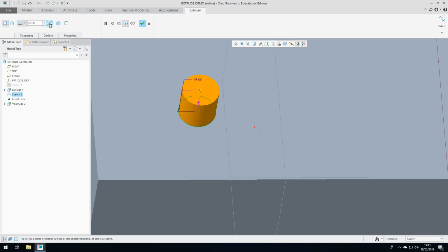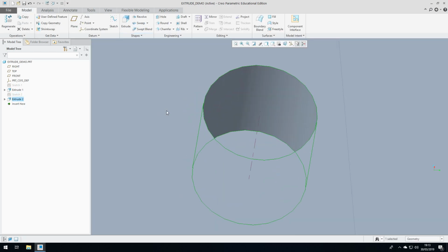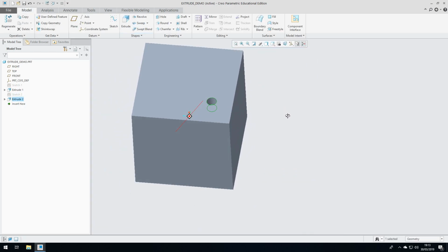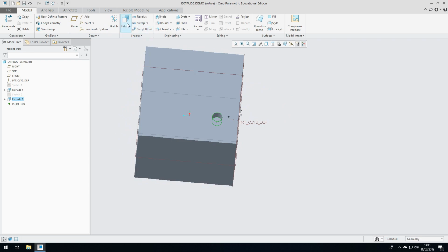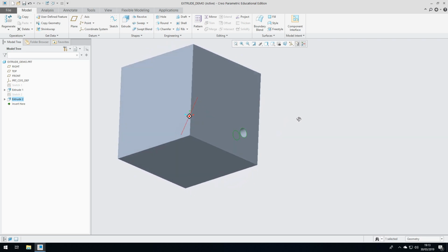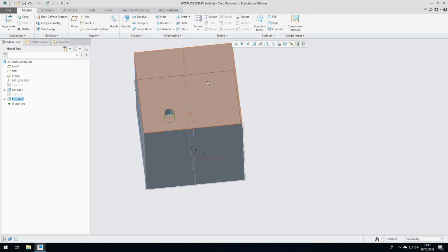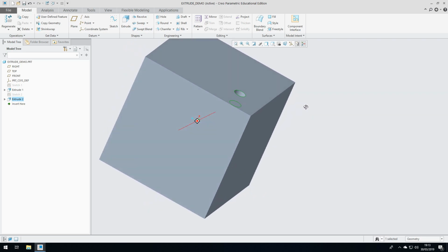And if you want to add it, if you just flick this button here, it will reverse the direction, so this now becomes 25mm positive, but in the opposite direction, and this will flip it, so it's reading the other way. And yeah, extrude is a very simple function within Creo. Some of the programs like NX have a lot more things you can do with just the extrude button, but Creo kind of has its own menus elsewhere for that kind of stuff. So yeah, that's your basic tools for sketching and extruding a model.